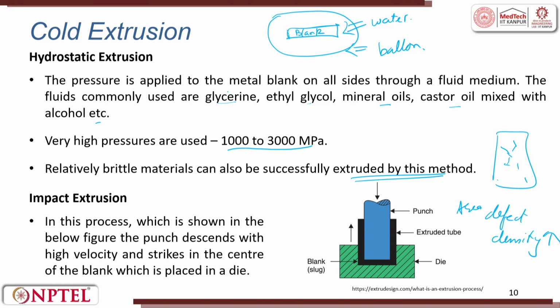Once you apply a hydrostatic pressure, these cracks are compressed. The moment it is compressed, it cannot grow. If it cannot grow, then you try to deform and get the output. So, that is called the hydrostatic extrusion process.